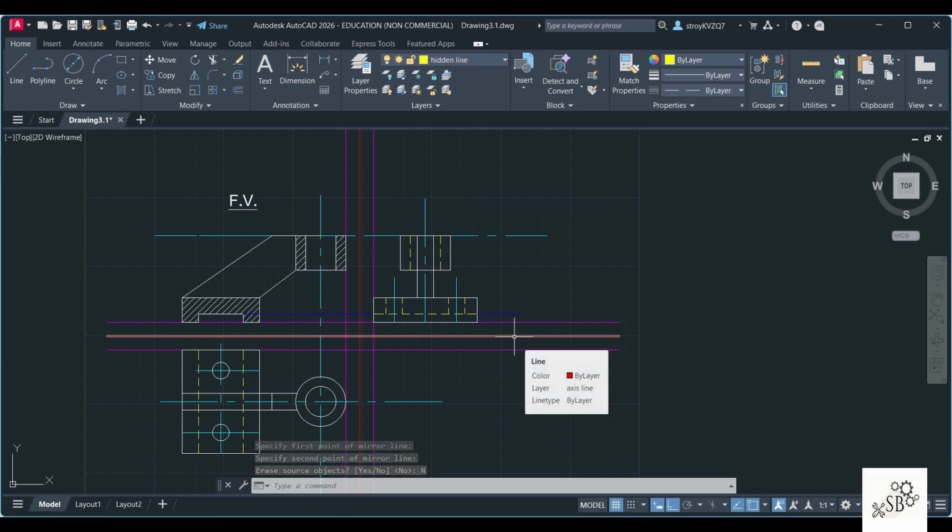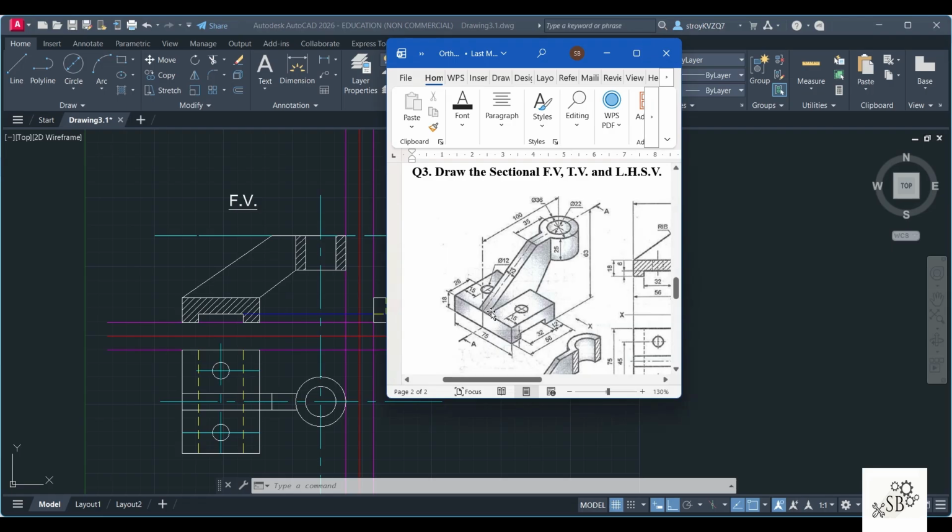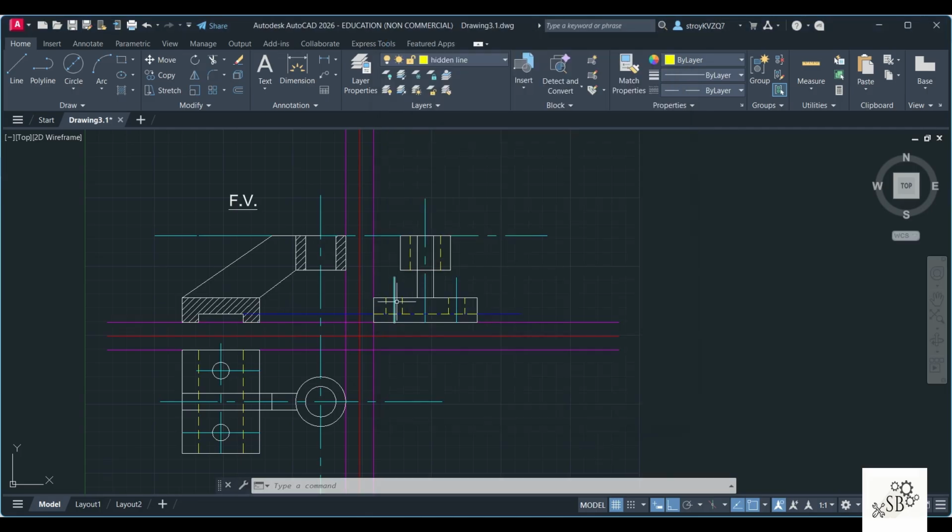So drawing the side view is actually quite easy. Now if you observe carefully, this rib at the back end is touching the surface at the back. So if it is touching behind, so obviously you will have to draw dotted lines again.